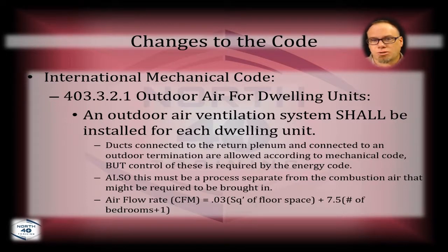Because when it comes to bringing in outdoor air for human occupancy, where does that air come from? Well, you look in the mechanical code. Mechanical code says ducts connected to the return plenum and connected to an outdoor termination are allowed. So we've got a collar on the return side and a little slinky that goes from the return side to the outdoor wall, and we've got a termination point on there.